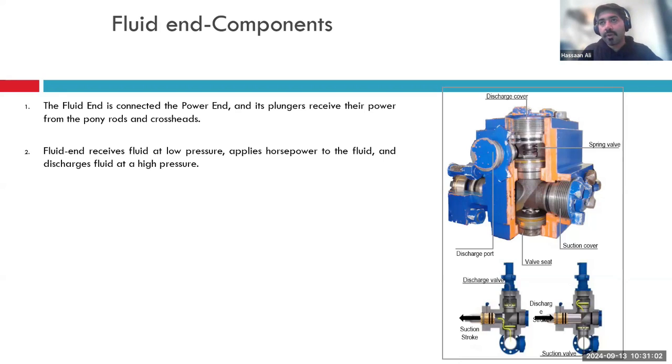One of the things about reciprocating pumps, which makes them very different from centrifugal pumps, is that if there is a blockage in the line, whether it's a discharge line or suction line, the pump will continue pumping and continue developing that differential pressure until something gives way. So you have to have either a rupture disc, pressure relief valves, or some of these safety features built inside your pump, to ensure that if there is an overpressure situation, a blockage, or something not working right, you will have some sort of pressure relief, because if not, it's going to blow up the power end.